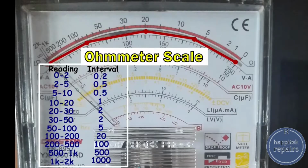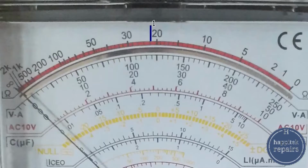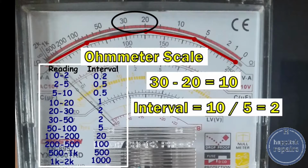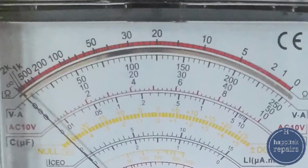Now let's have another example. We will interpret the range from 20 to 30. The number of lines from 20 to 30, we have 1, 2, 3, 4, and 5 lines. The difference of 30 and 20 is 10. Divided by the number of lines, we get 2, which is the interval of the range of 20 to 30. If we count the lines using 2 as the interval, here we have 22, 24, 26, 28. That is how we interpret the range of the Ohmmeter.